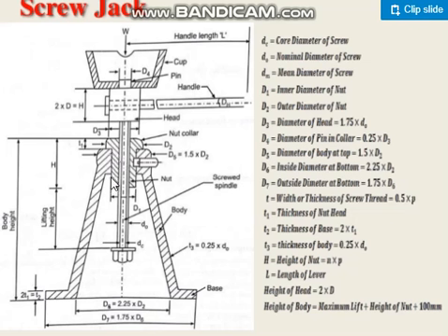So how is it put? Maybe some interference fit or some clearance fit may be there. But anyway, to ensure that it will not rotate, we are using this screw. A small grub screw we may use. This is how a screw jack is.